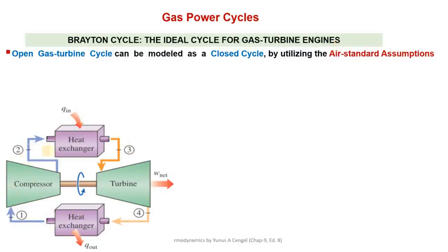So here we are assuming it is throughout gas, throughout air. So there is no combustion phenomena. We have replaced this combustion phenomena with heat transfer process, just like a heat exchanger. So heat is transferred to this working fluid, which is pure air, and similarly here the exhaust process is replaced with heat rejection process, that this fluid is actually rejecting heat to the ambient and then it is reused. So the actual process is assumed like a closed process, a closed thermodynamic cycle. So this will ease our mathematical calculations.